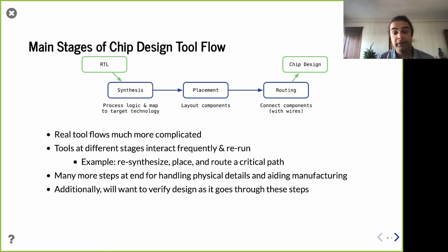So to ease that process, there's actually hardware in these chips that's used only for that moment. And then once you decide that chip passes the test, and you take it out and put it in a device in the actual product, it's never actually used, right? That functionality is somehow disabled. And that's there, right? So yeah, there's definitely stuff for this DFT. There's definitely stuff put in for testing.